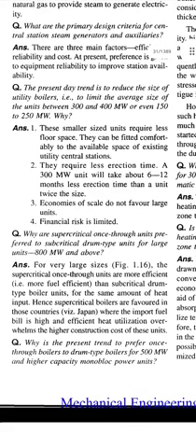Hence, supercritical boilers are favored in countries like Japan, where the import fuel bill is high and efficient heat utilization outweighs the higher construction cost of these units.